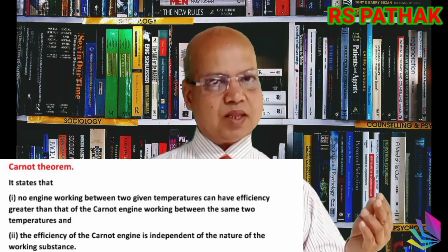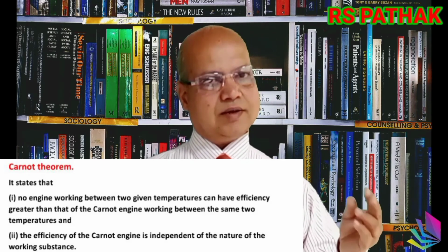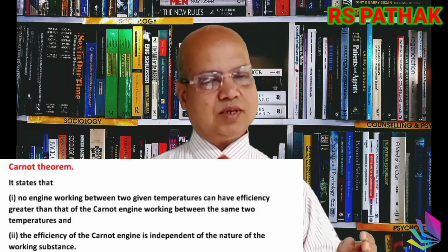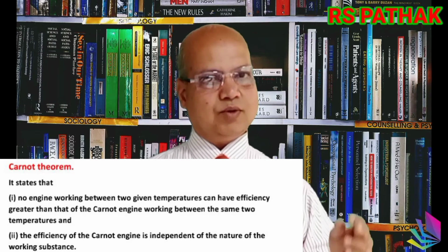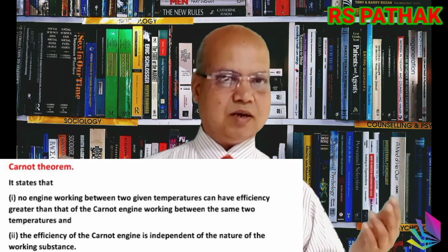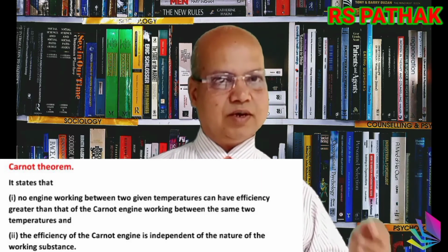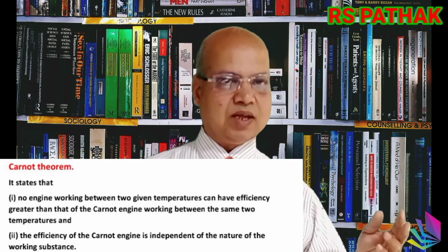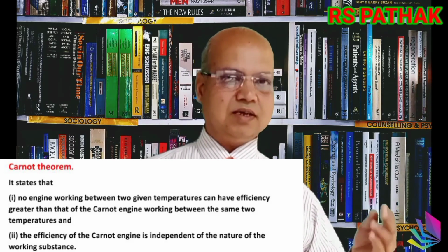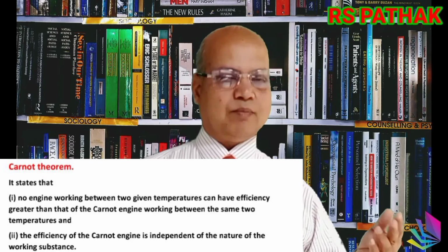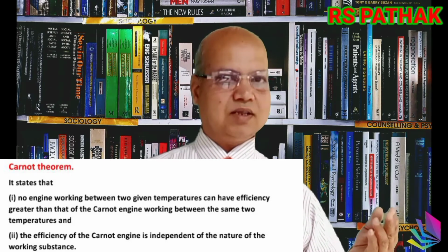I am repeating the statement once again. No engine working between two given temperatures can have efficiency greater than that of the Carnot's engine working between the same two temperatures. And the secondary statement is that the efficiency of the Carnot's engine is independent of the nature of the working substance. It does not depend on the nature of the working substance.